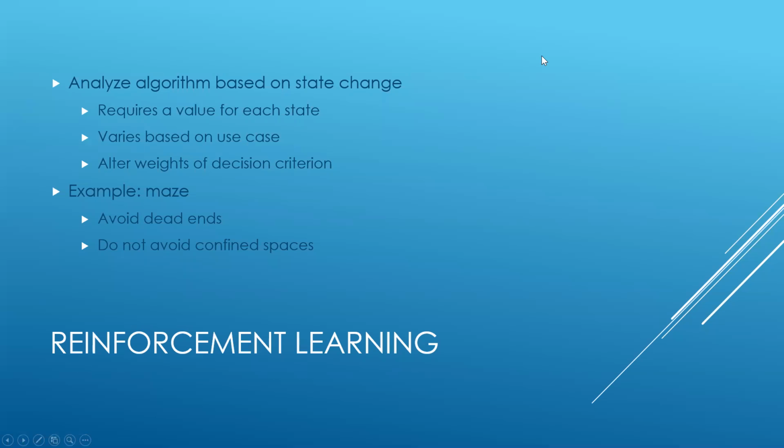A reinforcement learning approach may be applied such that the pathing algorithm assesses the results of its choice by interacting with the environment in its next state. Based on the level of improvement, if any, from the previous state to the current state, the UAV may find that it benefits from altering the weight of each decision criteria to optimize the path evaluation process based on the parameters of the current environment it is in.